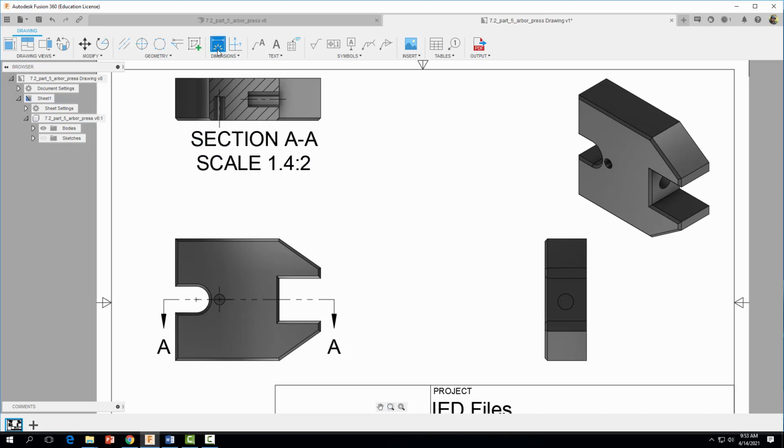All right, so now let's go ahead and start dimensioning. I'm going to grab my dimension tool, and I'm going to come down here to the bottom left border, and I'm going to use datum dimensioning. So I'm going to dimension from feature to feature, working my way across left to right. So I'm going to find this corner, click on it, go to my first feature, which is the center point, and move my mouse up and click where I want it. Right there.